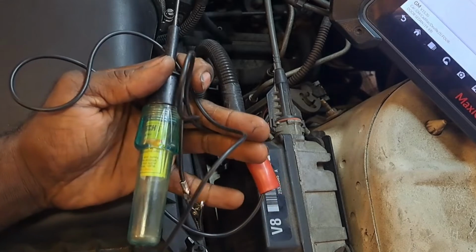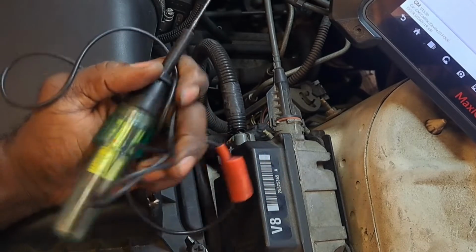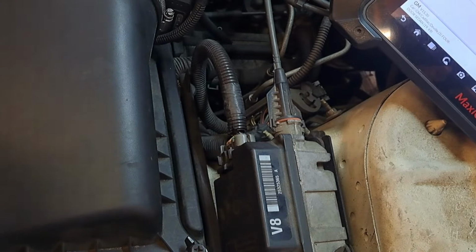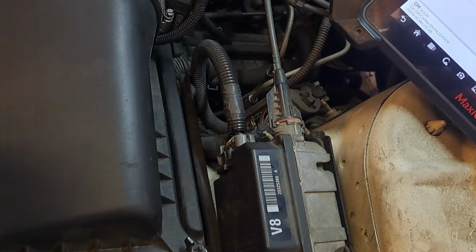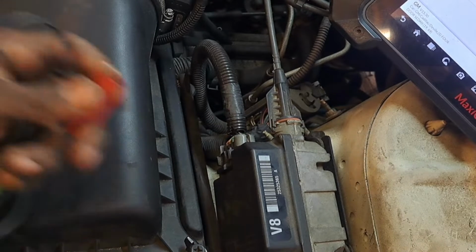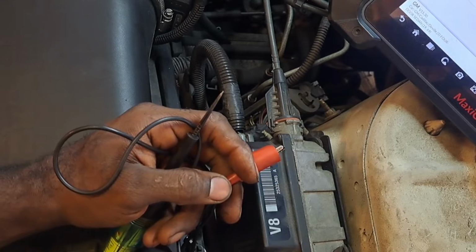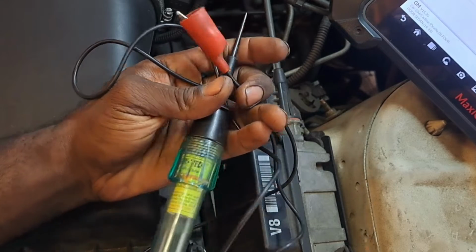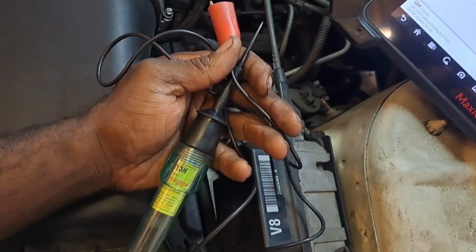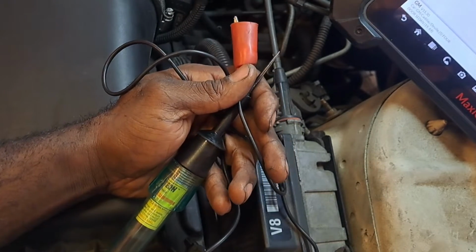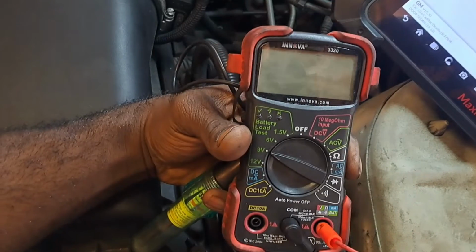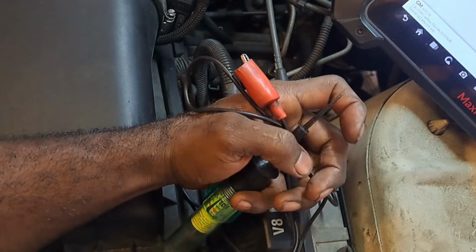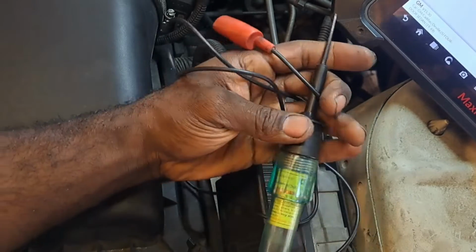It's very simple. You can use a multimeter, but it's best to do a load test on everything because it's possible you can get biased voltage. In this case, I'm going to tell you, it's not biased voltage. That wasn't a problem. But if you have to use a voltmeter, a digital voltmeter is fine for tracking wires, making sure you're on the proper wire, and continuity tests.